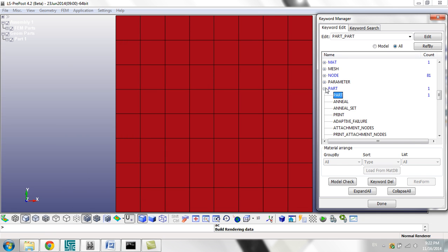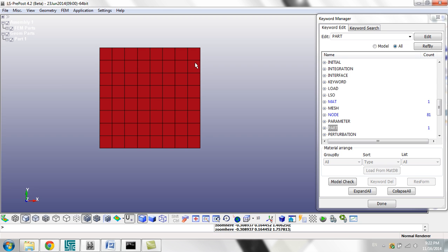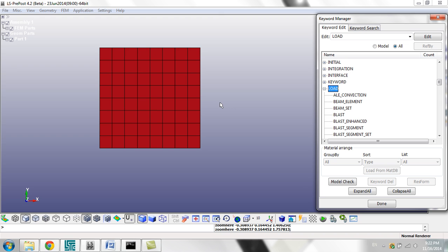We are almost there, but right now we want to define the load. This time we are going to define a new type of loading. It will not be a concentrated load. We will define here the own weight of the shell as the load. To do that, we go to load, and in the load first you have to define a list of the parts that you want LS-Dyna to include when it is calculating the own weight.